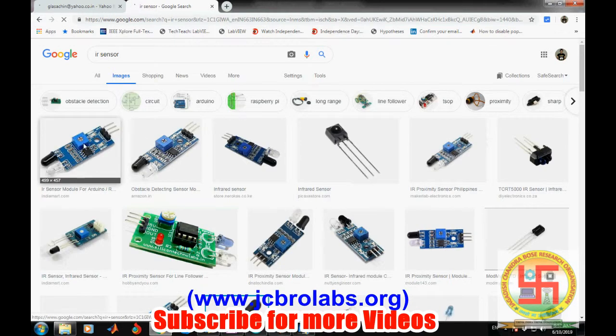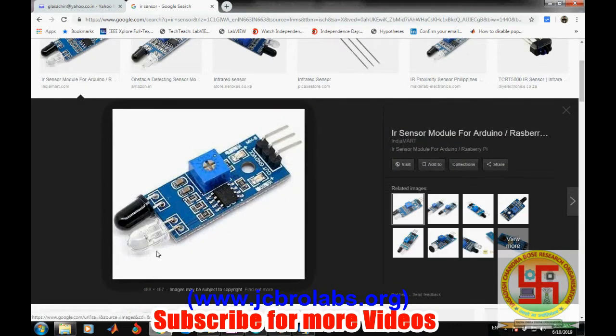Generally this is the IR sensor which we use for Arduino interfacing. One is the IR LED and one is the photodiode, and they are placed next to each other. If there is no object in front of it, no IR radiation comes back to the photodiode, and this sensor will give 0.